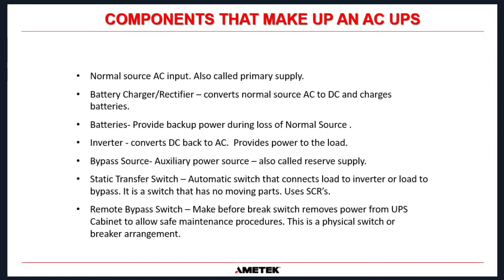So on Ametek SCI UPSs, it is nearly always a rotary switch that has 3 positions, and they are normal, bypass to load, and isolated bypass position, but they can be a physical breaker arrangement as well. Some other UPS manufacturers use breaker arrangements instead of a rotary switch.